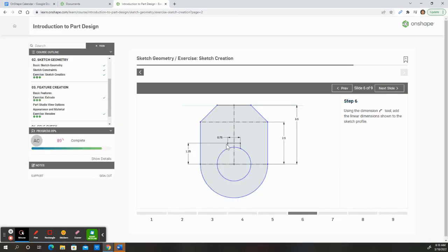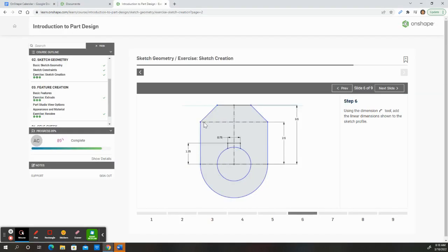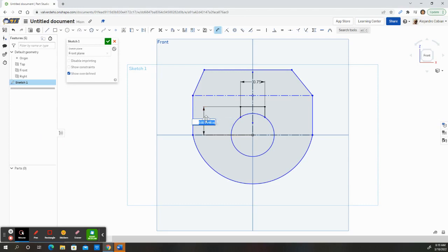So now we have this height from this bar to the center, the origin. So let's click on dimension again. And let's actually move that outwards. We can leave it there, but we should have put this on the outside. Let's actually practice good habits. Delete. Let's try that one more time. All the way out here. We want 1.25.